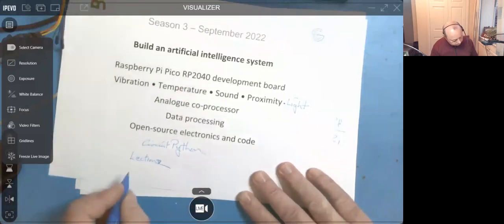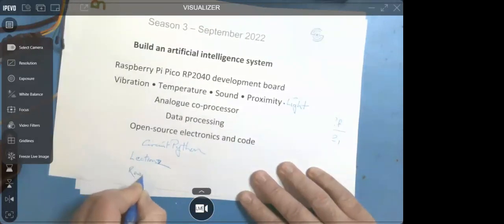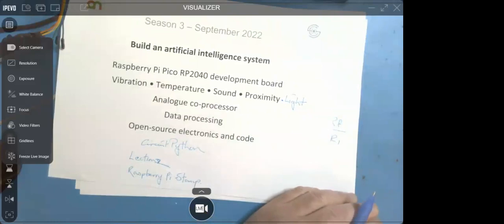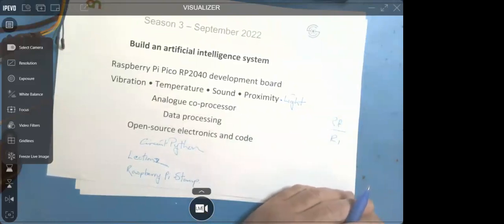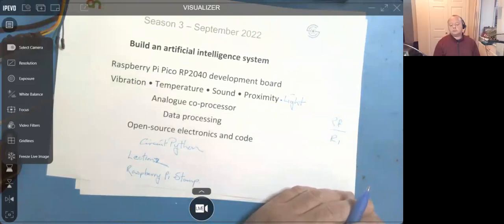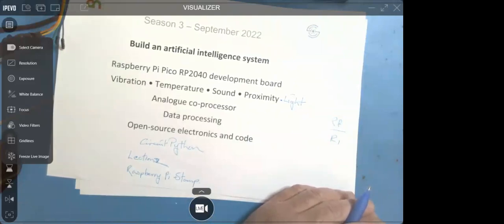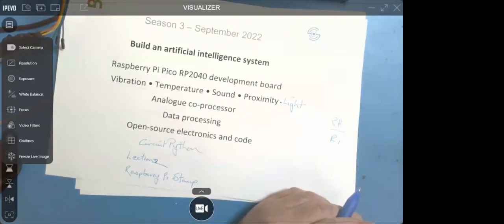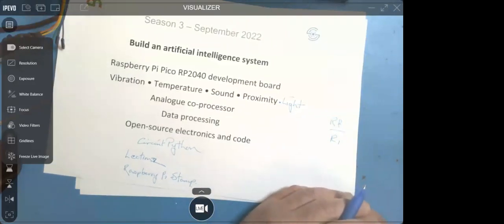It's very, very comparable to the devices that you can get from the Raspberry Pi Foundation, so the little boards you've just been looking at. Except that it actually has all of the RP2040 IO pins available, because the one you've just been looking at doesn't have all of them. No. In particular, the ADC3, as in the fourth ADC input, is missing.